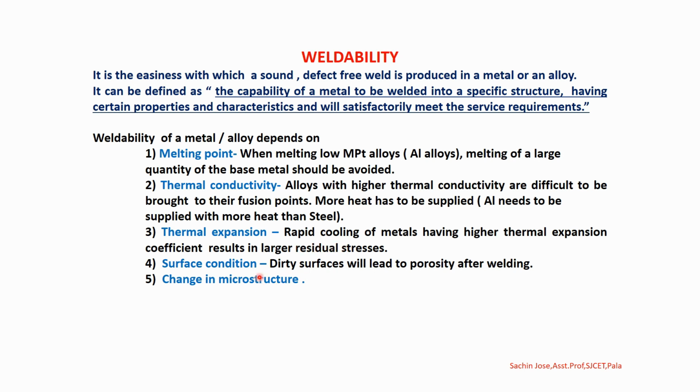The fourth point is surface condition. Surface condition is another issue. A dirty surface will lead to porosity. Porosity is what? Blowholes, or porosity, are voids or empty spaces, empty bubbles inside the joints. So a dirty surface will lead to porosity.